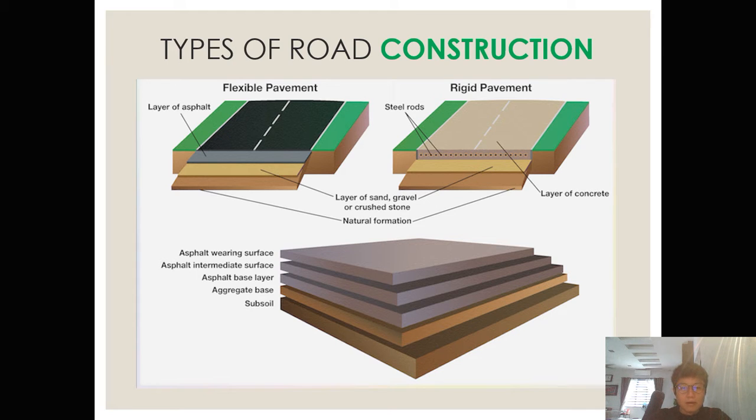The first slide here is showing you the two typical pavements that we have. One is a flexible pavement and the other is the rigid pavement. As the name tells, you will be able to imagine. Flexible means when the traffic load is traversing along the road, you come across movement that can rebound, right? The temporary movement is like an elastic, when the tyre comes, it goes down, and when the tyre has passed, it will rebound. Whereas if it's a rigid pavement, such a movement will not take place.